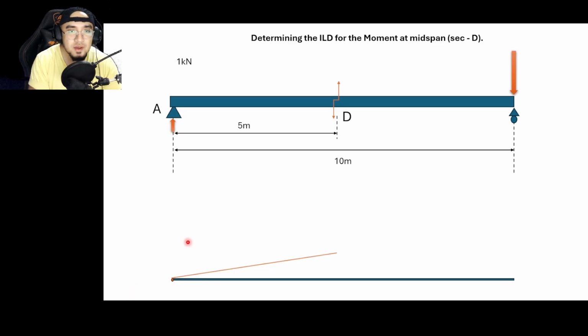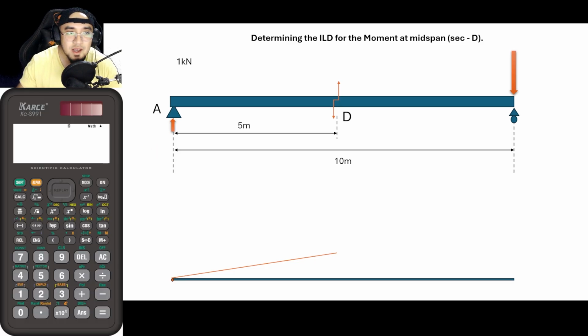However, guys, as you can see here, since this load is exactly at the top of this support, this support would now be carrying all of this load. And if it carries all of that, there is nothing left for this other support. So again, if this support reaction would be carrying 100% of this load, the result for AV is basically equal to 0. So it becomes 0.